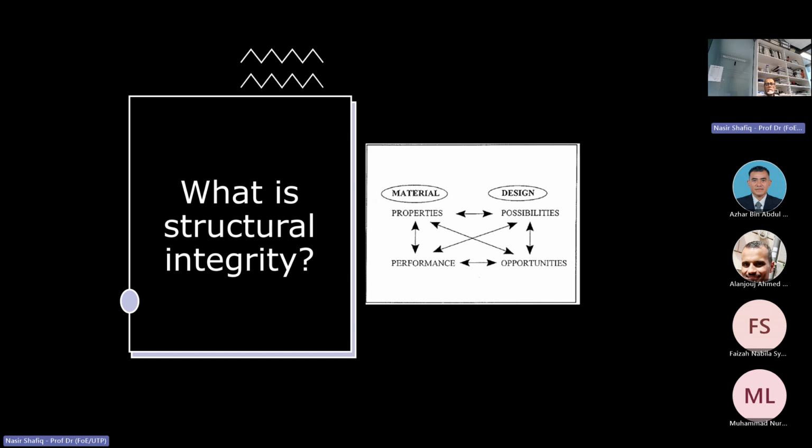So what do you do? First you have to do the flow requirement, and from the flow of the pipeline you can estimate the diameter, which will be 500 internal clear diameter of the pipe.